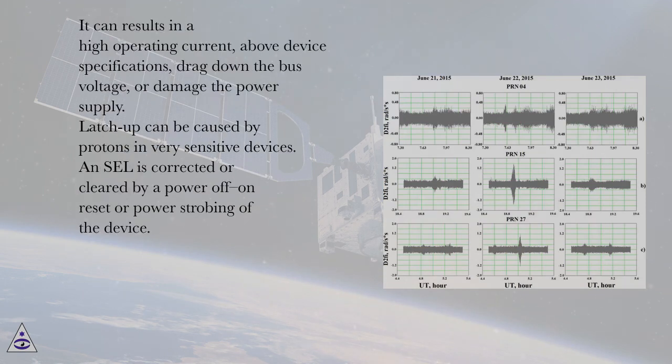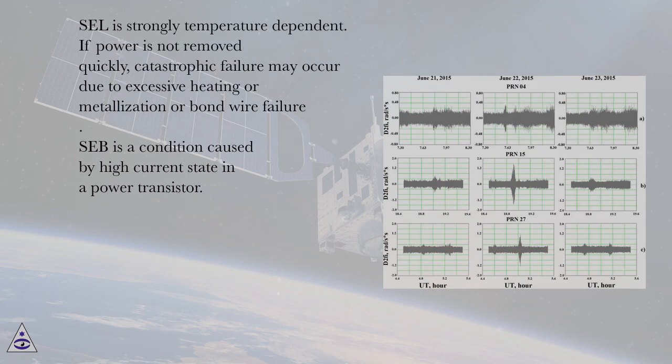It can result in a high operating current, above device specifications, drag down the bus voltage, or damage the power supply. Latch-up can be caused by protons in very sensitive devices. SEL is corrected or cleared by a power off and reset or power strobing of the device. SEL is strongly temperature dependent. If power is not removed quickly, catastrophic failure may occur due to excessive heating or metallization or bond wire failure.